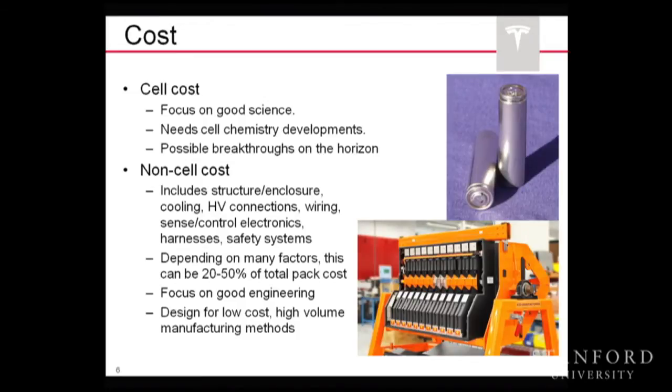Turns out, and I don't really understand the whole story, but I'm guessing that all the laptops in our laps and on our desks here have driven the development of this particular cell, this lithium ion 18650. It's 18 millimeters in diameter, 65 millimeters long. It's a single cell that gives 3.7 volts nominal, and anywhere from a few watt hours, maybe up to as many as 10 watt hours or something like that.